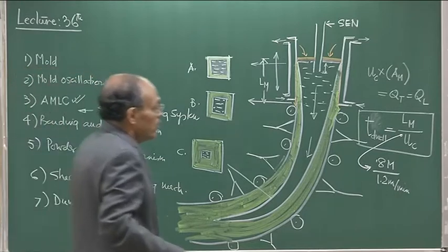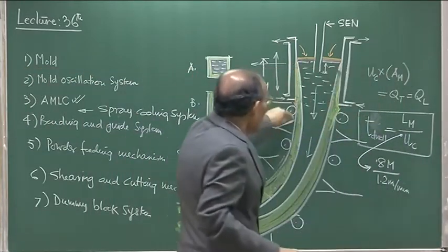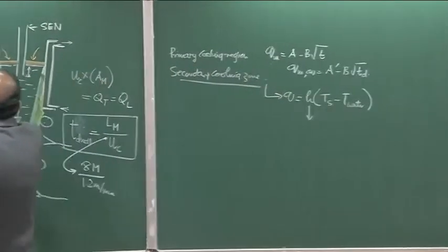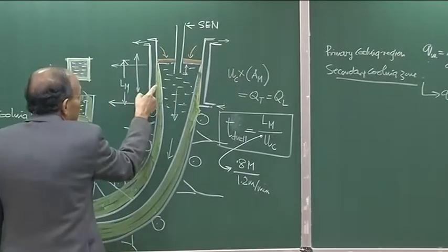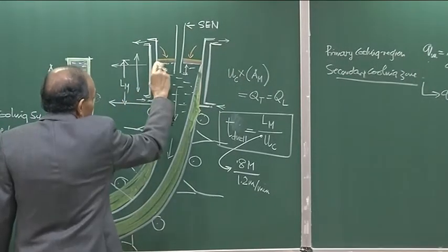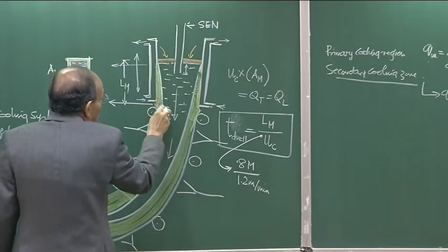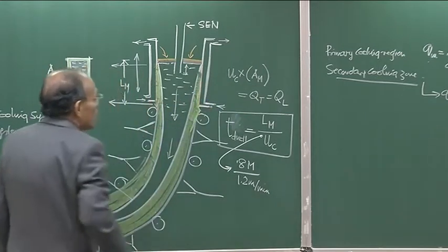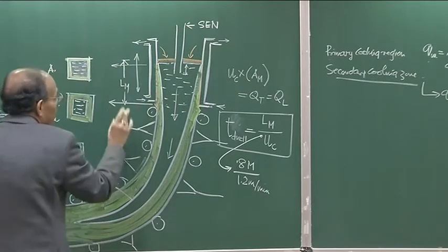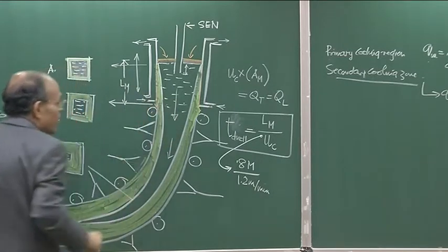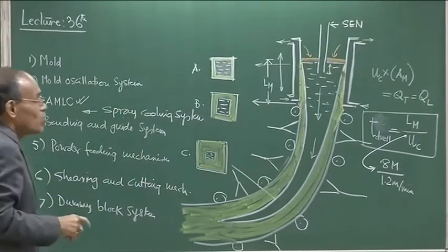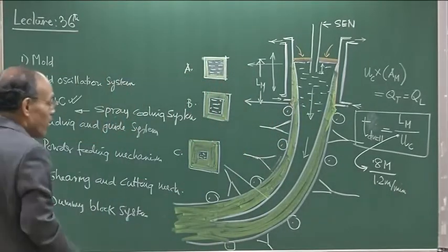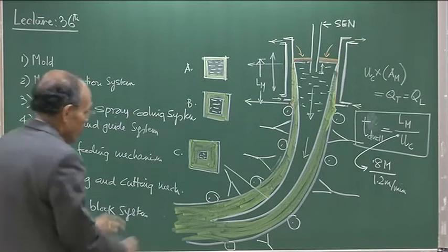Now, in the mould, the heat transfer flux is maximum here, and the flux decreases in accordance with the equation. Because the distance and time here are more and the casting speed is constant, T is less here, medium here, and large here. So, in accordance with that equation, the flux is smaller here, and that is quite legitimate, because we would expect the resistance to heat flow to be larger in this case, because we have a thicker shell and also a somewhat thick air film or powder film between the mold and the casting surface.